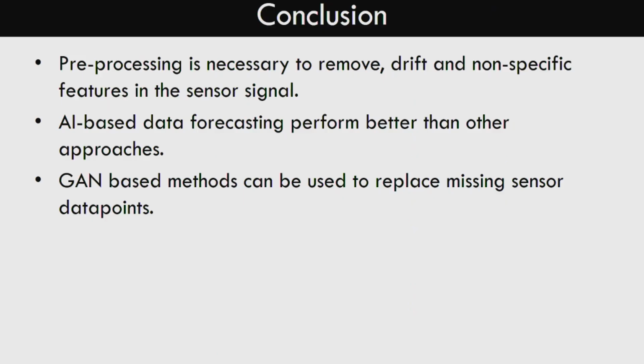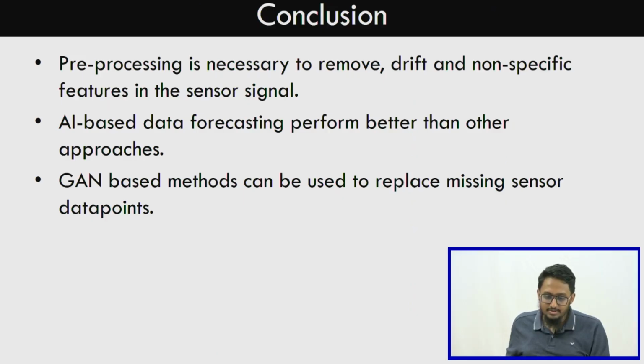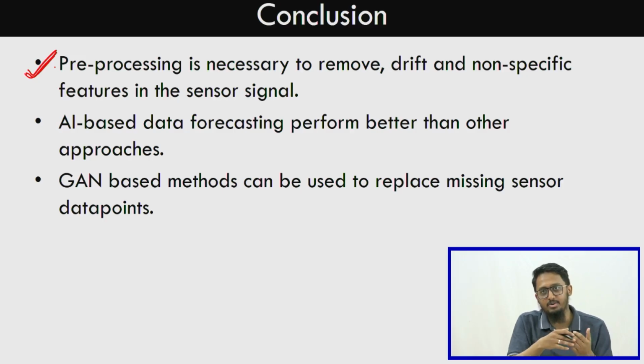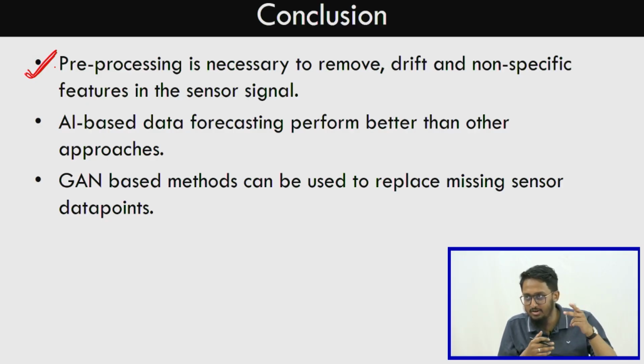Right. So, what we have covered broadly in this topic is, we require some sort of pre-processing in the sensor, especially if you are using wearable sensors. So, we have to account for linear drift, we have to account for nonlinear drift, and also nonlinear drift which has a similar profile to the target analyte of interest. Linear and nonlinear drift which are not similar to the peaks that we observe, the rate of change, we can easily remove using a simple mathematical model.